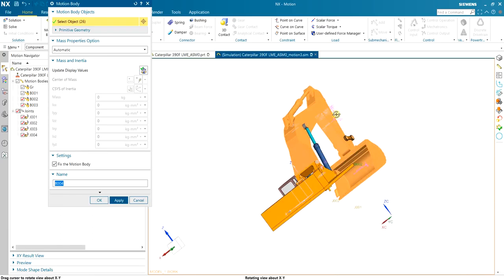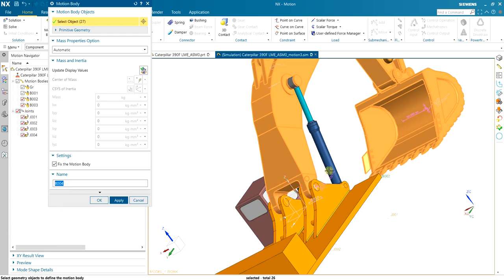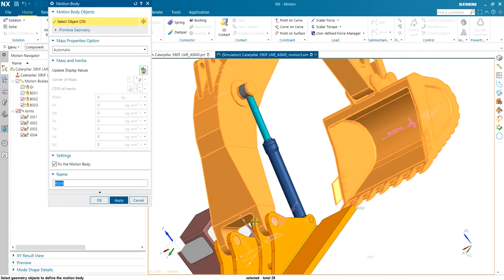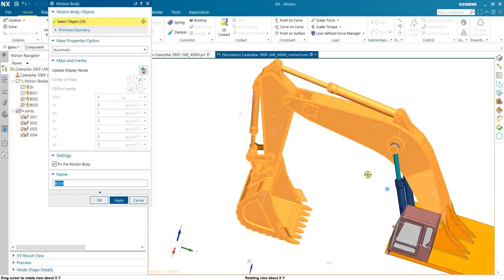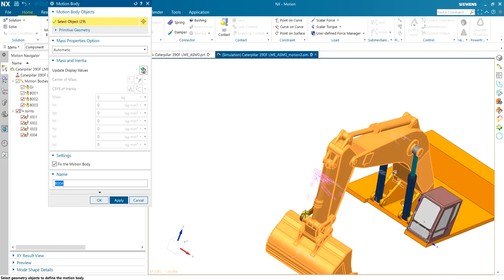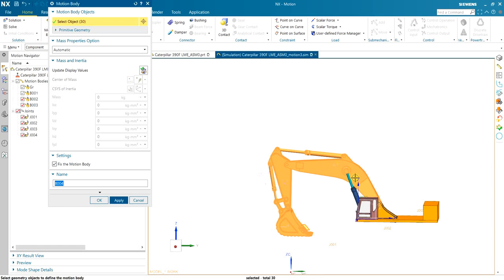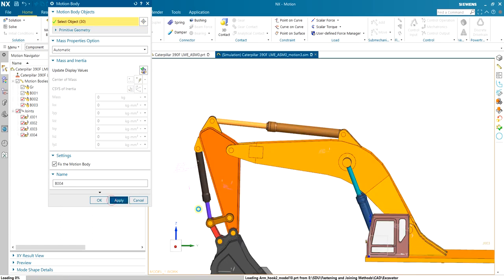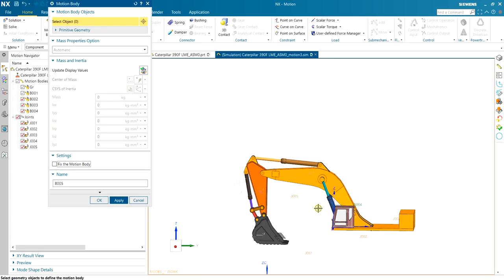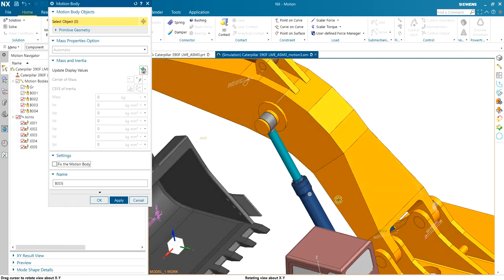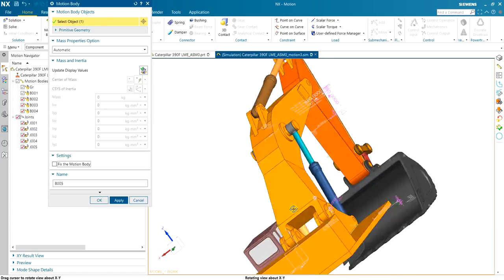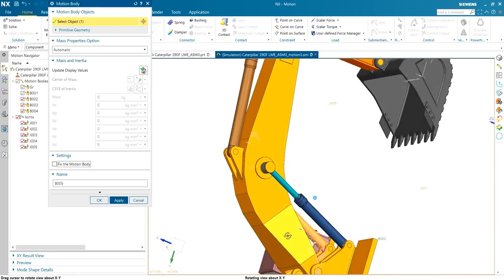Also this part and this part and the pins as well. Except these parts, they will push the bucket up, the bucket and the rest of the parts that are selected. Let's apply. I left this fixed checked, so we have to go back and uncheck that later. The only part we needed to be fixed is the ground. And then we have this acting as one part.